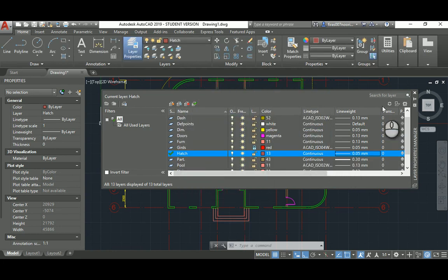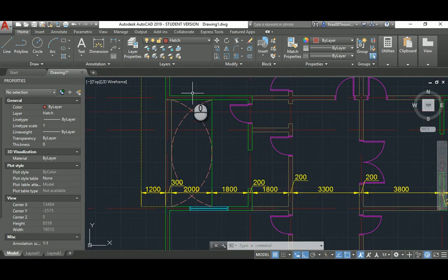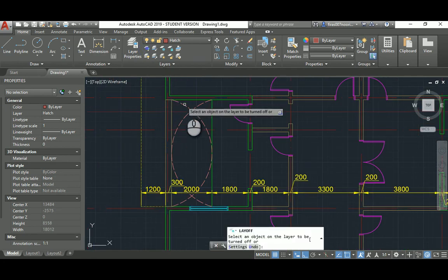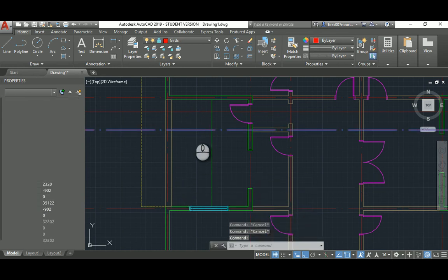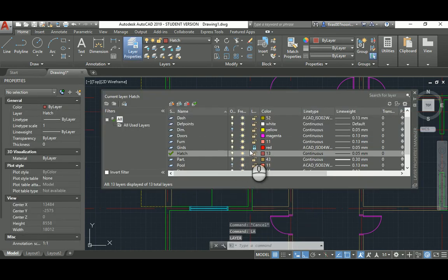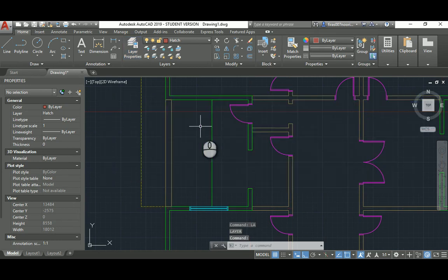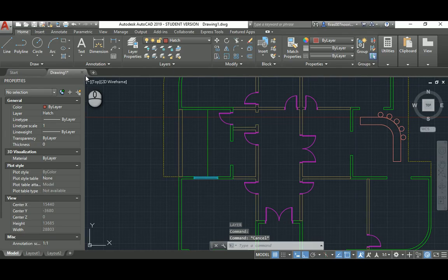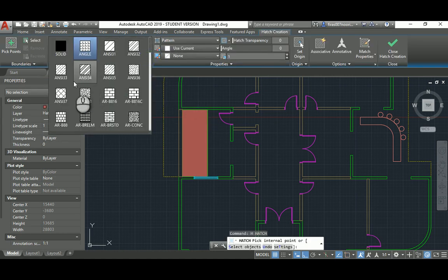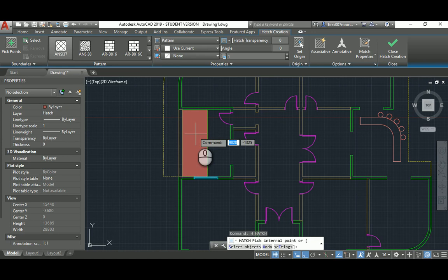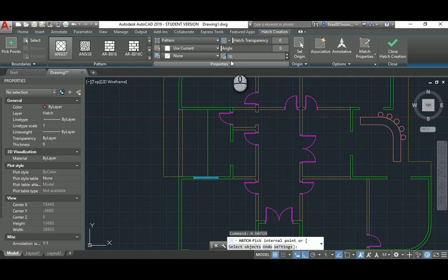Good. So those lines, and also the dimensions, will stand in the way, so it's a good idea to turn them off with the grid. Just turn it off here. So now what type, just rotate the grid, so H space, and pick up the style you like, this one. If you don't see the pattern, just go ahead and hit 10 and then hit enter. Now try to see it, not 100 and enter. Much better, so that's what we want.